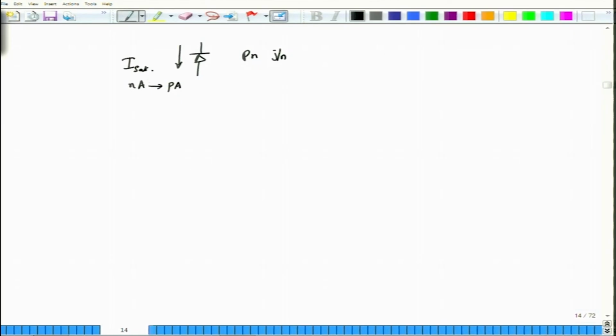But this is also a current, right? And because of this current, on an average, there will be a noise that is generated, which we will call sigma_d squared, which is the variance of this one. Or if you are not comfortable with that, I can write delta i_d squared on an average, and I will give you the value of this as 2q I_d bar times B_E. The terminology in photodetectors is slightly different.